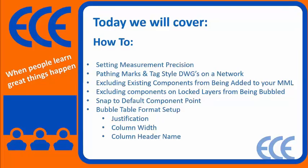We'll also look at a way to exclude components on locked layers from being bubbled. A lot of times, we just want to bubble certain areas in our drawings. So we'll look at locking layers and just putting marks and bubbles on components in paper space that are unlocked.